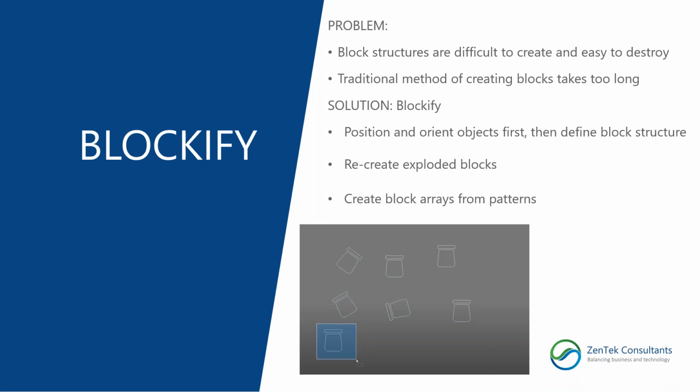And as a result, to turn that exploded block back into a block, you have to reinsert that block, or in some cases redefine the block, and then delete the objects and replace them with the block in the proper orientation with the correct scale. So that's one of the major problems with working with blocks. It takes time to make a block, and it's very easy to remove a block.